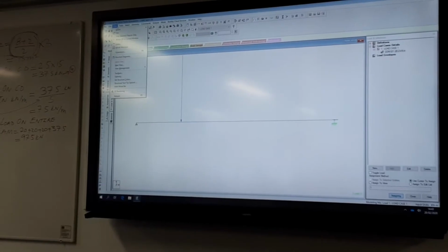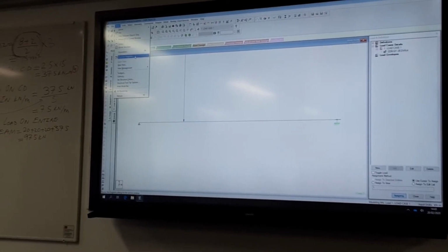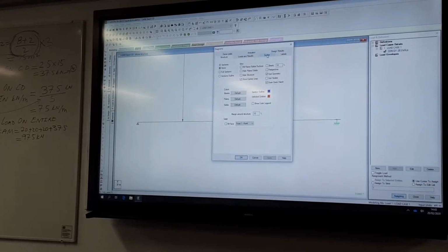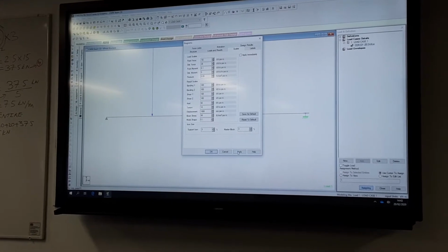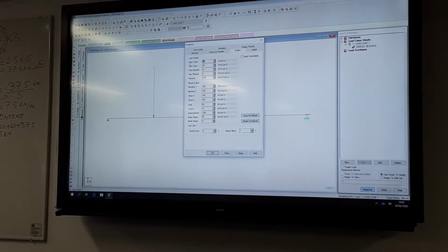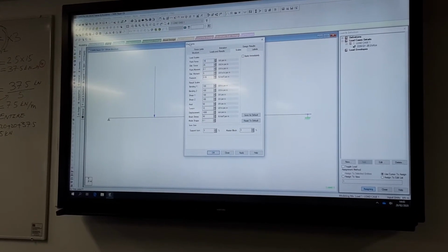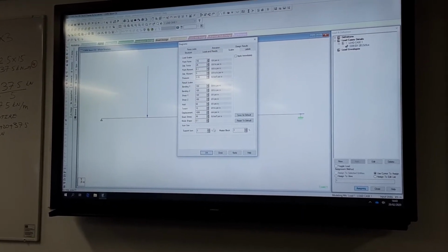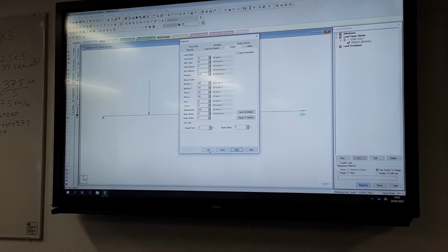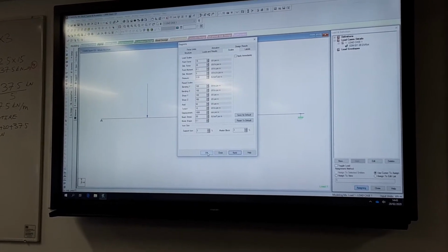Obviously you can control this by going to structure diagrams because this load looks quite big. For the point force, if you say 10 and then apply, it is looking a little smaller. If you click on scales and load scales and enter 15, then it looks quite reasonable, isn't it?